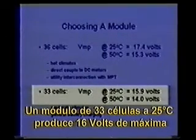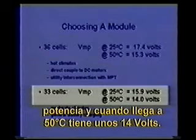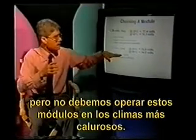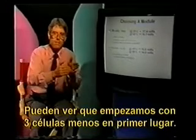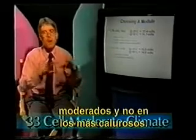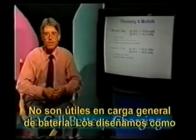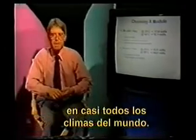A 33-cell module produces at 25 degrees about 16 volts max power voltage, and when it heats up to 50 degrees C, it has about 14 volts. This is still enough to charge a 12-volt battery, but we shouldn't operate these modules in the hottest of climates. You can see we begin with 3 less cells in the first place. So 33-cell modules should be used in moderate climates. In other words, not the hottest climates. They're useful for general battery charging. We've designed them so that in most climates around the world, a 33-cell module will be acceptable.